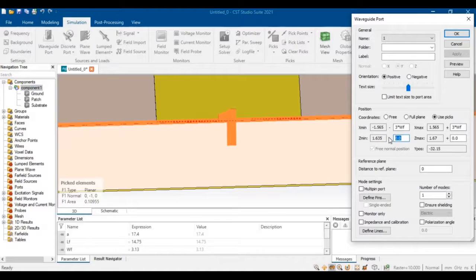Similarly, this is basically the minus symbol, and we will use the value 1.6 because we are at this point and we have to touch the ground. So this is the height of the substrate, and we will be at the bottom edge of the substrate, and further we will add the plus sign, but minus plus will again be equal to minus, and we will subtract 0.035 in order to touch the bottom side of the ground, so that it is properly radiated.